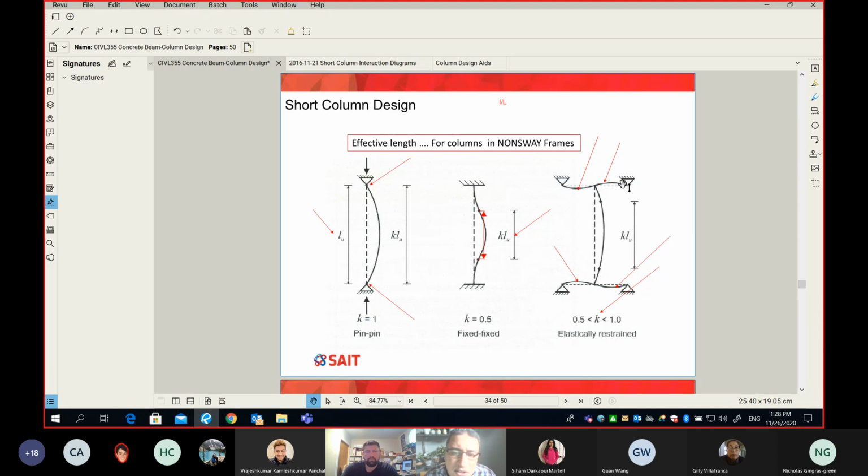If you have a member that is fixed only from one end, for example like this, let's say I have here a column that is a cantilever column, which is not really very common to make. It happens for pylon signs and flags. Those are cantilever columns. So when you think about the buckling shape, guess what? This is how the column will buckle. And if you want to come up with the full sine wave, this will make the buckling length L twice the length of the cantilever. Very, very uncommon, very rare.